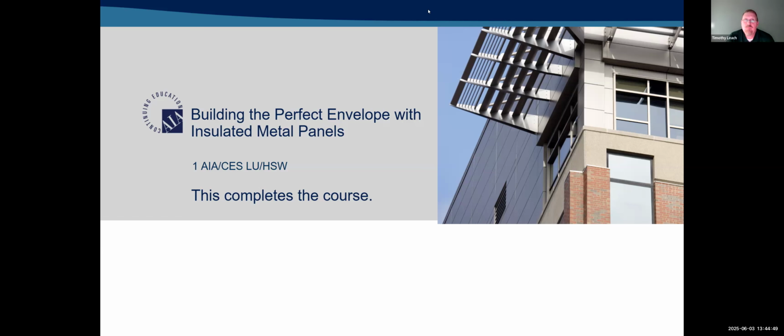Okay, so IMPs have good fire testing considerations. However, a polyisocyanurate insulated foam does not provide your 1, 2, or 3 hour fire rating. You can use an insulated panel with layers of gypsum to create that fire rating.